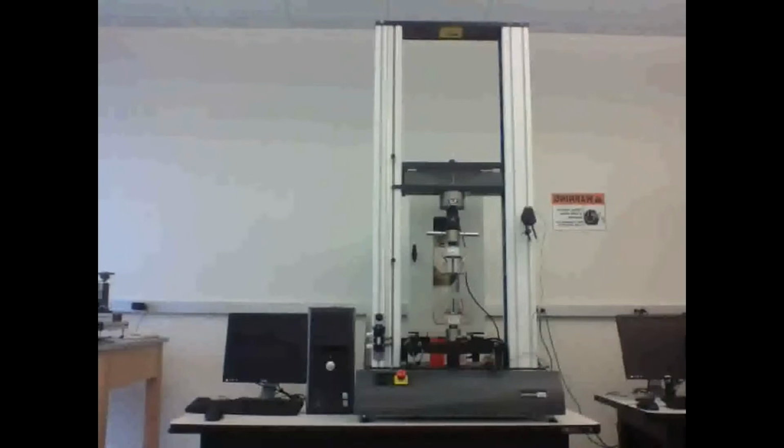and the final specimen. For this lab, you will need a 6-inch flat tension specimen of both 4130 steel and 6061 T6 aluminum. In this lab exercise, only the teaching assistant will operate the Instron 3369 universal testing machine. For both the aluminum and steel samples, the UTM software will simultaneously record the force information during the test.